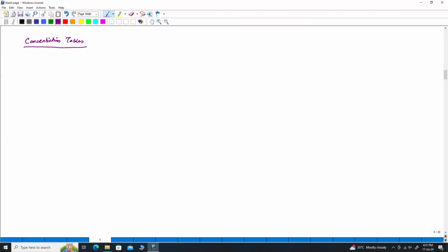product end. So what happens is, when we are feeding the raw material, these tables are shaking in the direction of the riffles itself, and water is being charged. So there are two forces that are normally observed when we are seeing the concentration shaking tables, as we call them, tabling process, shaking table. So the table itself is moving, and there is the flow of water. We will see how really the particles are getting separated out, and how we are getting various types of feeds in this concentration tables. So we know that there are riffles.